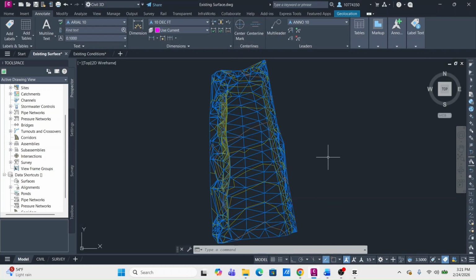So now that we have this put together here, if you're wanting to define the shape and define the road and so on and so forth from here, you're going to want to create feature lines and break lines. So real quick, a feature line is a 3D line that has elevations that you can use to control grading. A break line is a line that controls how the surface triangles form, and it tells the surface where there's a sharp change and so on and so forth.